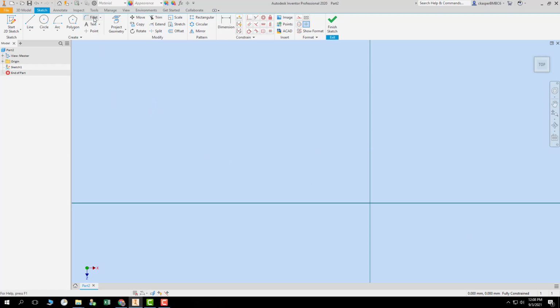Let's do one more, fillet. No, we'll save fillet for when we start doing extrusions. No, I tell you what, let's do a fillet anyway. Let's make it a 3 for a triangle. Draw ourselves a triangle here and just briefly show you what the fillet command does. It really works with objects that are extruded, but it also works with objects that are not yet extruded.